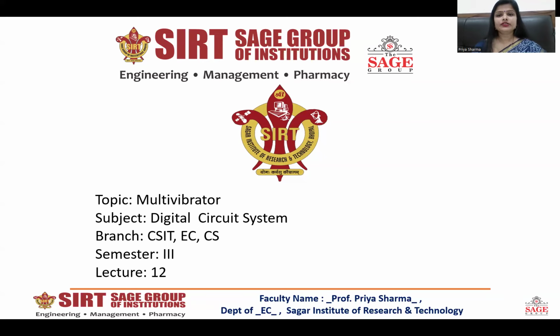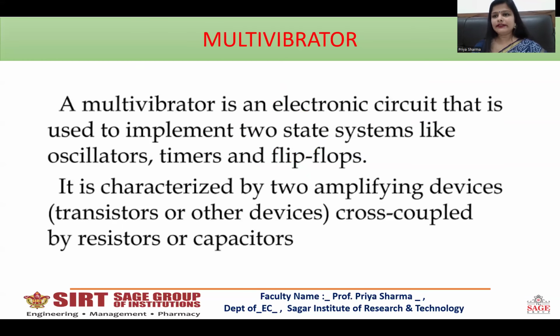So, this is our 12th lecture of the lecture series on the Digital Circuit System subject, which we are going through. The 12th lecture will cover multivibrators. So, basically, what is a multivibrator? A multivibrator is an electronic circuit that is used to implement two stable systems like oscillators, timers, and flip flops. It is characterized by two amplifying devices like transistors or other devices, cross coupled by resistors or capacitors.